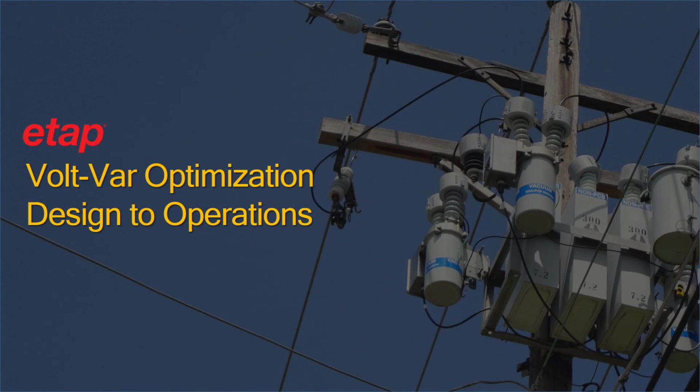The webinar today will cover volt-var optimization or VVO. VVO is the process of optimally managing voltage levels and reactive power to achieve efficient grid operation by reducing system losses, peak demand, or energy consumption in any combination.